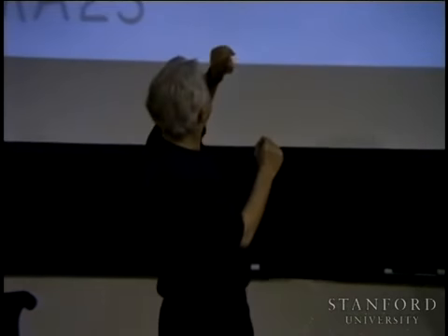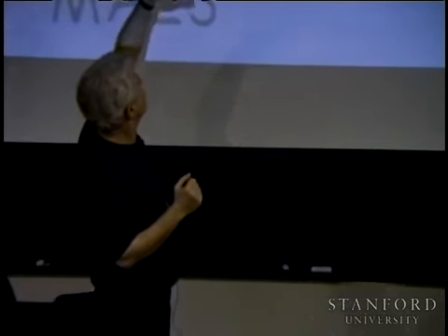But all we are going to use for this is a very simple description that, again, will allow you to take a look at this robot and say, oh, these are the dynamic characteristics of this joint, and you can almost see the coupling forces between the different joints in a visual form that all depend on those axes of rotation and/or translation of the robot. And this comes through the explicit form of dynamics that we will develop.